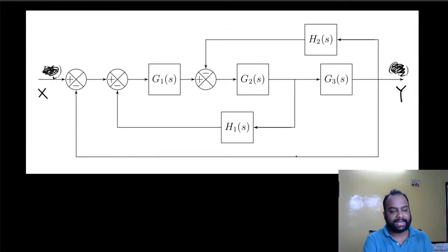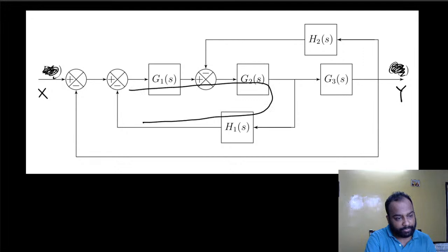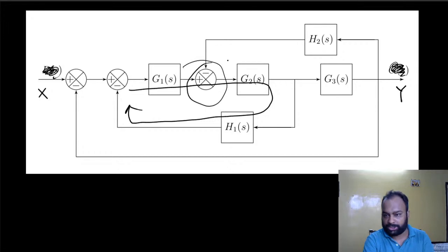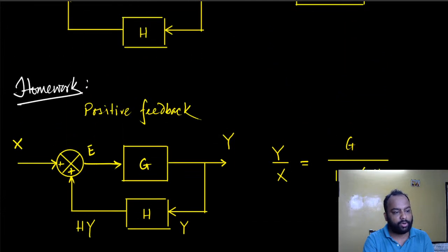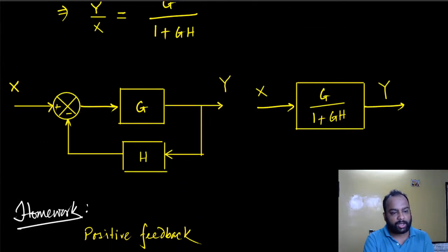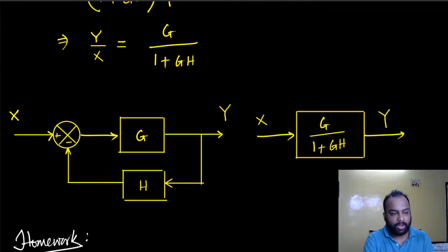Right. With that said, let's try to figure out how we can actually reduce the block diagram, right? So now try to understand a few things very easily. So we have a feedback loop here. But if we clobber everything together as a feedback loop, unfortunately what would happen? All these intermediate signals will be lost, right? So there is one important point you need to remember, is that when we constructed the equivalent system here, all these intermediate signals were lost essentially.